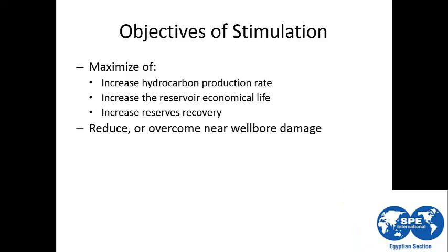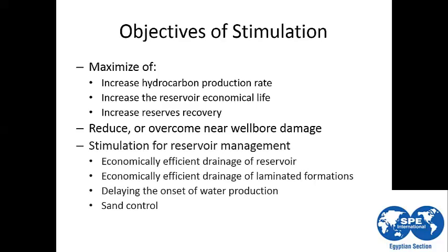First of all, increasing the hydrocarbon production rate and the reservoir's economic life by decreasing the abandonment pressure, so that we can keep the reservoirs producing under this pressure. Increasing reserve recovery by reducing the abandonment pressure means we will increase the recoverable reserves from the reservoir. Also, the objective of stimulation is to reduce or overcome the near wellbore damage.